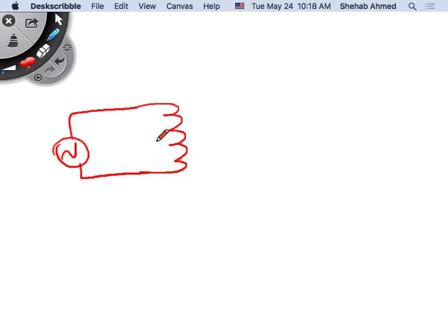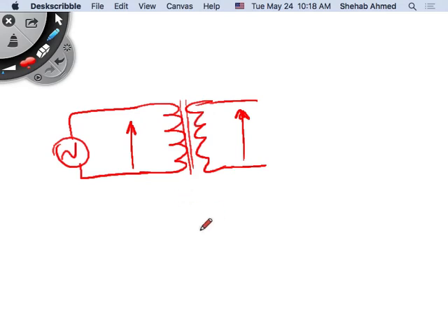Not yet. So a transformer is a device that converts voltages and currents from one side to another set of voltages and currents on the other side, while preserving power. Fine, there's some power loss. Is it mutual inductance? No, it is not. Does it convert AC to DC? No, but it's an AC device. Okay, we'll wrap up with this, explaining what this is.